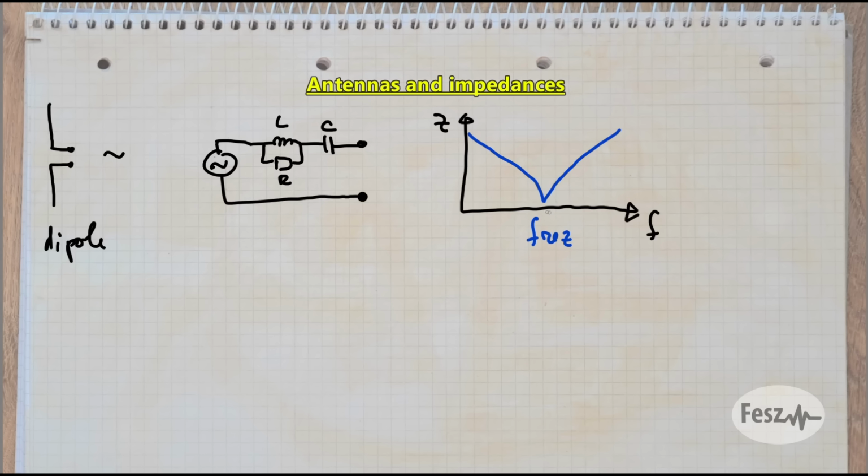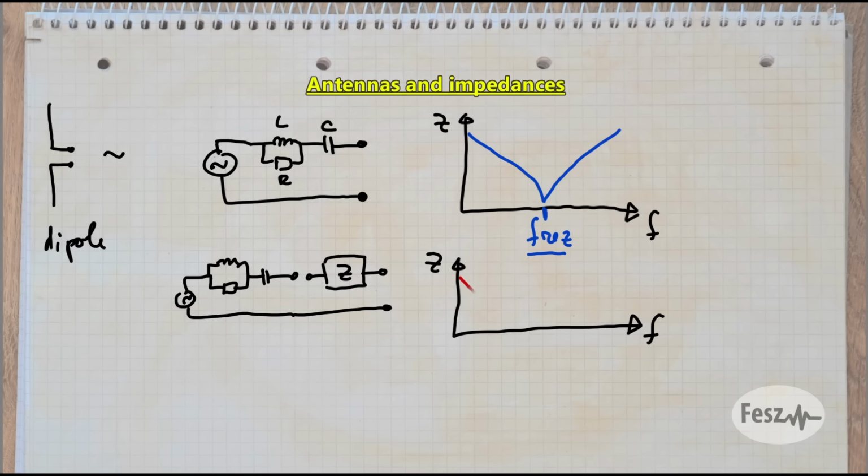With no matching, we would use this antenna at, well, the resonance point. Everywhere else, its impedance is very high, so signal pickup is greatly reduced. Now, without modifying the antenna, you can add some extra reactance and shift the usable point. Adding some extra inductance, we can move it lower, or with some extra capacitance, move it higher.